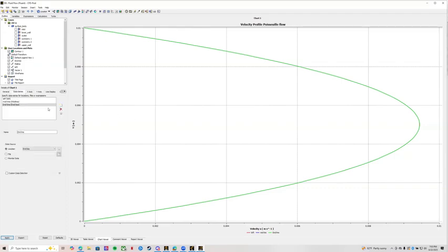Mainly, if I go through here and delete, let's say, the end line part, you can still see your midline, and then you press apply. You can see that the end line and midline are all overlapping, because by that point we can see that the flow is already developed. So in this case, we're just going to add back that end line part. But by the midpoint, we see that the flow is fully developed, so the velocity is going to follow the same profile.